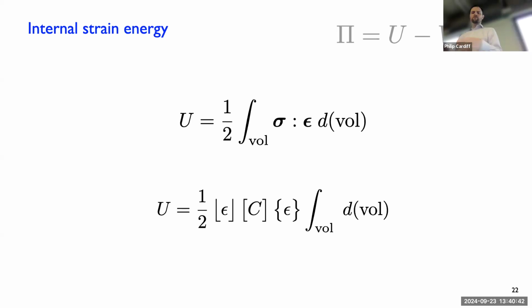One thing I'm not going to go through so much in this course, but which happens in practice, is this idea of Gaussian integration or Gaussian quadrature. The idea there is, if strain or C does vary within the element, then how do you calculate this integral? The approach used in finite element methods is to calculate the value of that integral at certain points, like the center of the element or a few locations within the element, and that lets you approximate the integral. If it did vary in some higher order fashion, you add the values at four points in the element and take some weighted sum of them. That's so-called Gaussian integration or Gaussian quadrature. I'm going to avoid that, but it's something that gets used.